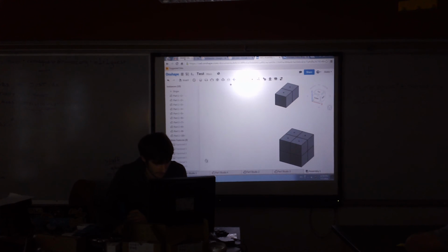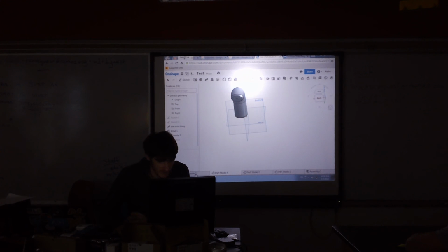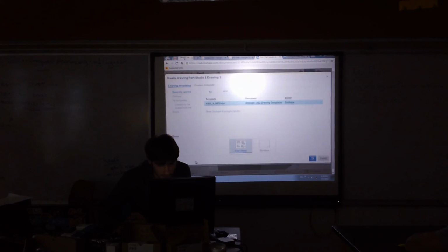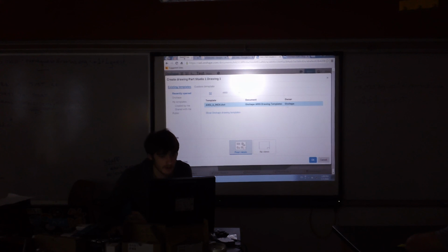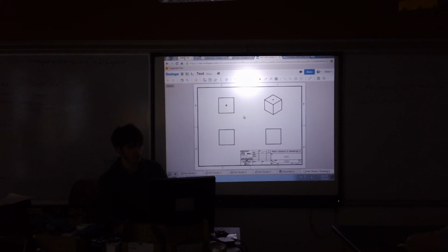One last thing, if you have something that looks pretty, I guess we could just do this box, and you want to put something professional looking on your website, you just right click it, create drawing, the front view is good, add dimensions, and when it's done, you will have a professional looking drawing. Now, can you imagine that on the website? That looks pretty nice. Right? So I would highly recommend making drawings with dimensions, and we'll get more in depth there when you need to.